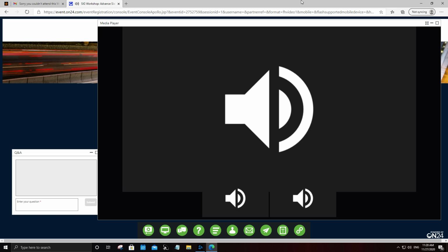A question is whether live load reduction is considered for this. Yes, we can consider it, and in this case, yes, we were considering the live load reduction. Once we use the software, in the design strip section there is a tab for live load reduction. So you might want to go there and give the criteria, and it will consider the live load reduction.